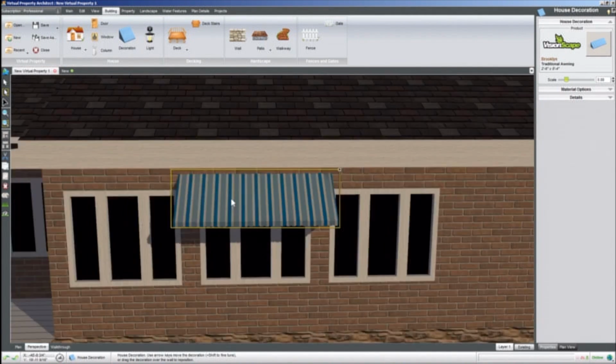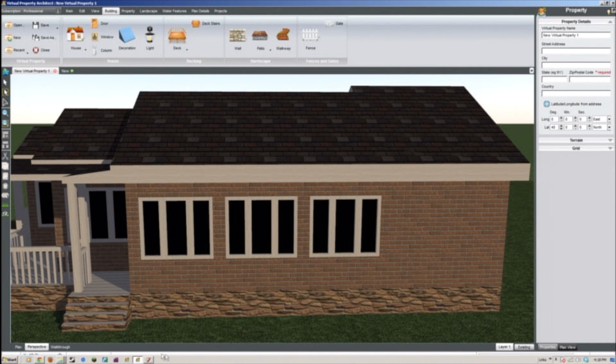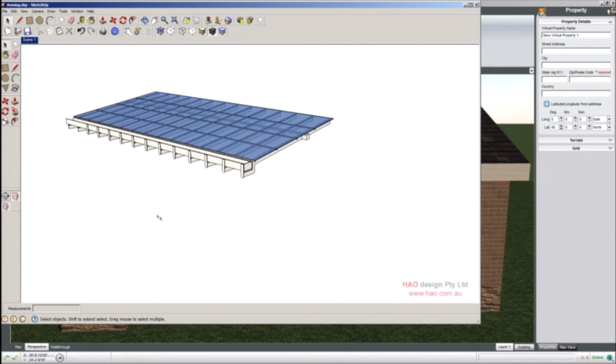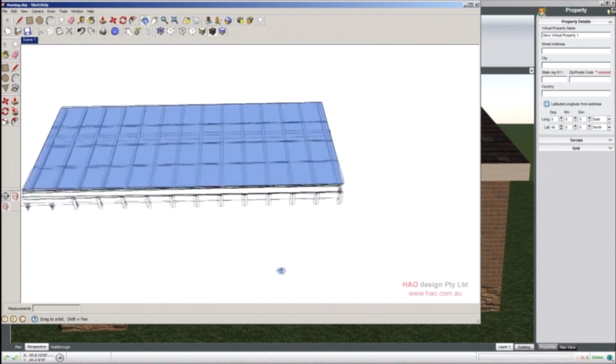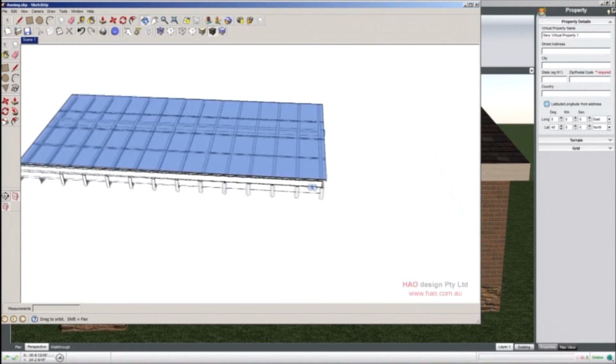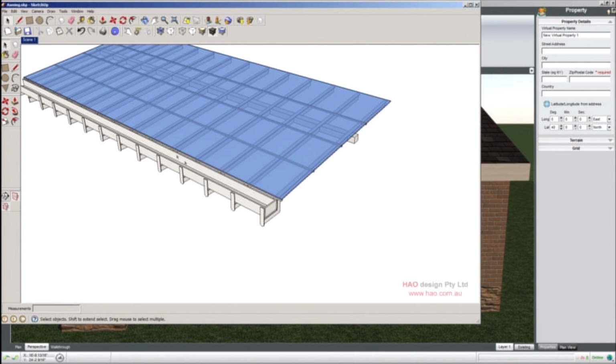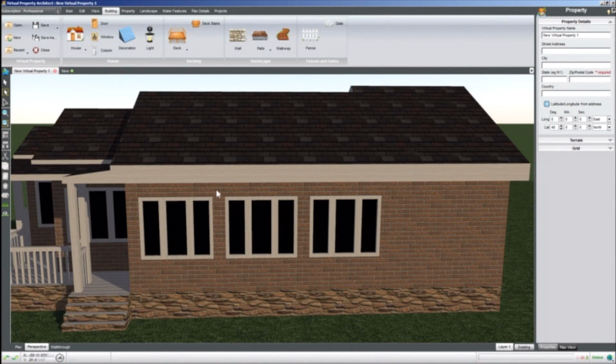But we want to allow you to use the SketchUp model library as a functional model library. So for something like this, you might not necessarily want to use a Visionscape awning. So, say you have something like this fancy glass awning that I've got here. I've done a very little bit of prep work just to make sure that the material groups are okay. I've exploded this, worked with the materials, and recombined it. So let's import this as a house accessory.